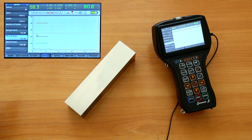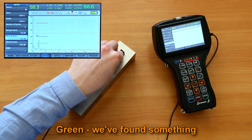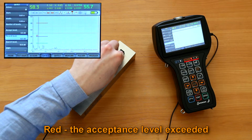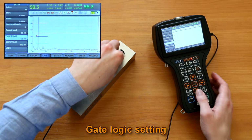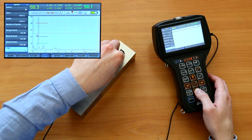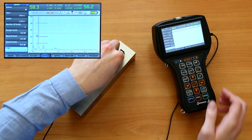just observing alarm LEDs. It's turned green. We've found something. Blue. We are to record the indication. Red. The acceptance level exceeded. This saves us time and attention. Let's concentrate on scanning. Further, we can find the gate logic settings, which let us use it either for pulse echo or for through transmission or echo images techniques.